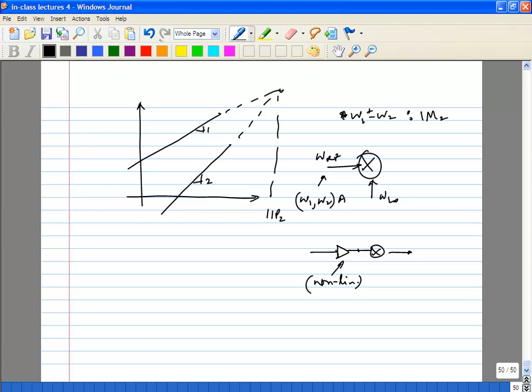And what you will see is, since you are all designing differential circuits, ideally your IIP2 will be infinite, okay. Ideally, if you have differential circuits, because you don't have any even order components, at the end of the day your IIP2 will be limited by your mismatch, okay. That's why I said in the project assume a 1% mismatch, right? So you will see IIP3 numbers we saw were like what, minus 5 dBm and plus 5 dBm, right? Whereas IIP2 numbers will be plus 40 dBm or plus 50 dBm, something like that.